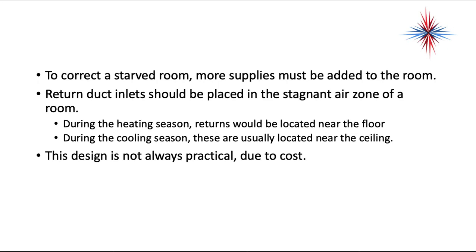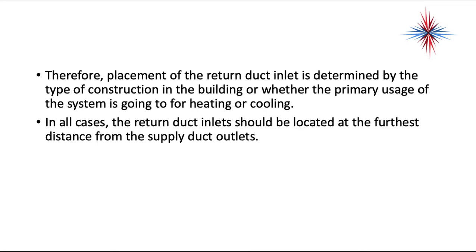Okay, this design is not always practical due to cost. A lot of times we do have to pick one or the other. So you look at what you do more in the space. Are you heating or are you cooling more often? Therefore, placement of the return duct inlet is determined by the type of construction of the building or whether the primary use of the system is going to be for heating or cooling. In all cases, the return duct inlets should be located at the furthest distance from the supply duct outlet.